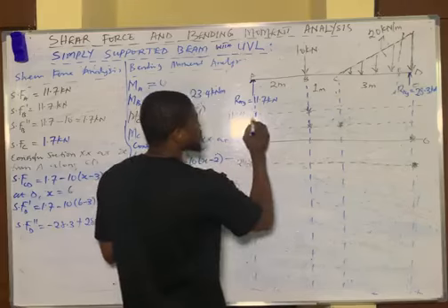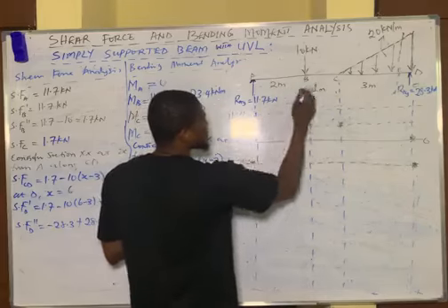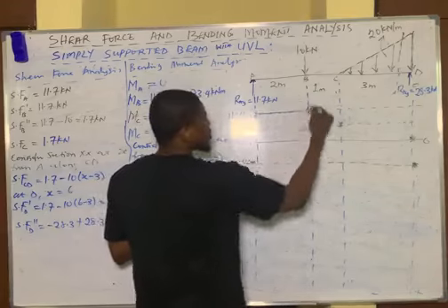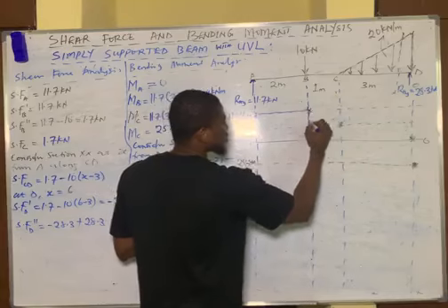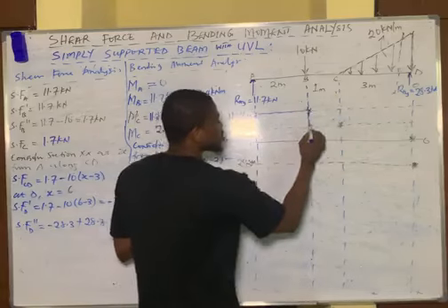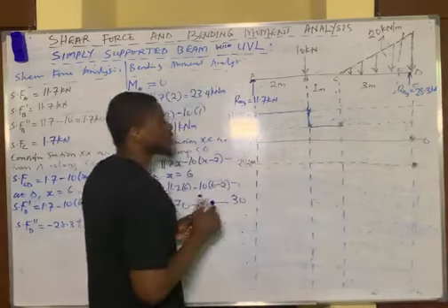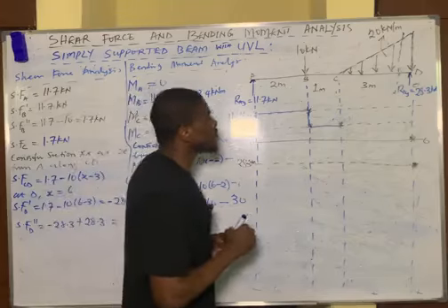Same thing, that same force moves from point A to point B initially, still a point load. So you connect these two points. Again, still a point load acts down, so you connect with this. This same load moves from point B to point C, you connect. But now you have a UVL.